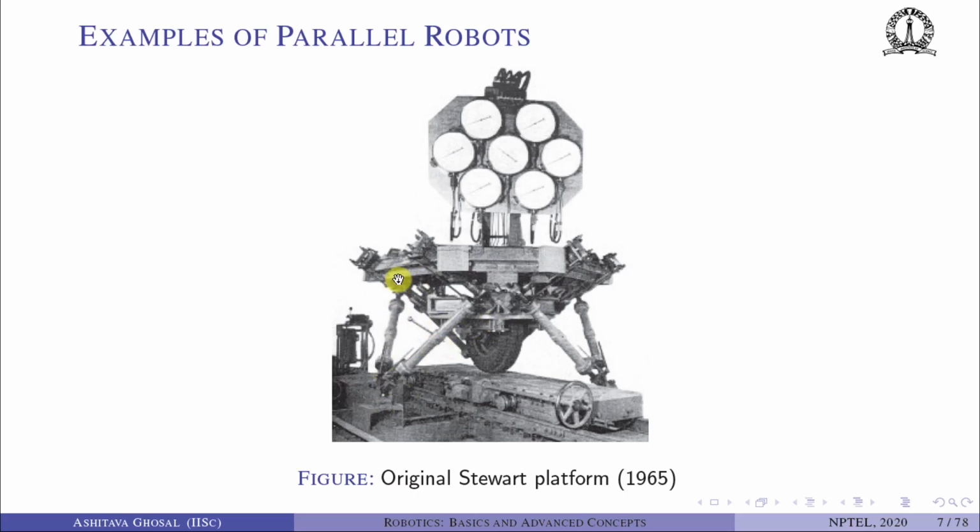At the 2 ends there is a hook joint and a spherical joint. So this is a UPS arrangement in each leg. There are 6 of these legs, and by sliding the prismatic joint we can make this top platform go up and down, have X and Y Z motion, and also 3 rotary angles, okay, roll, pitch, yaw, for example.